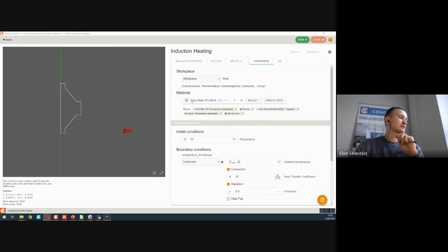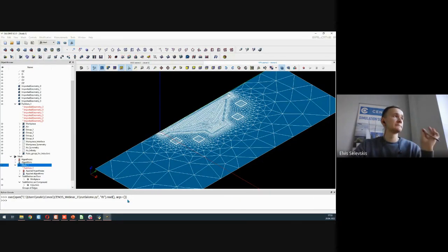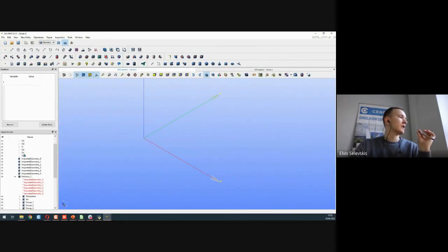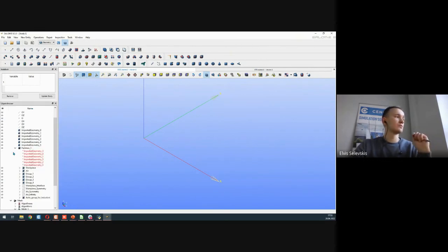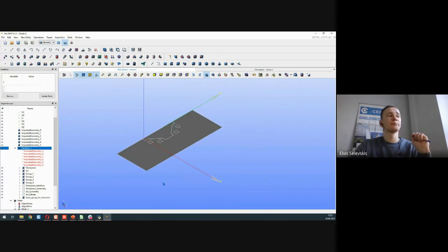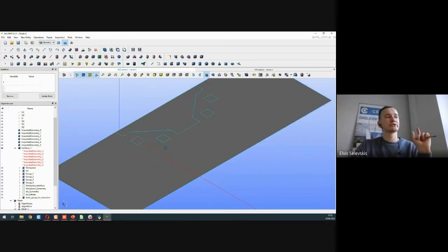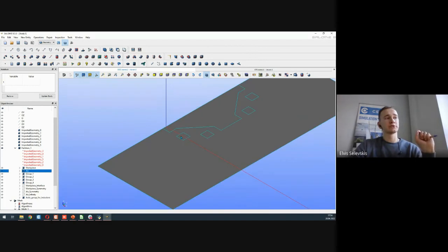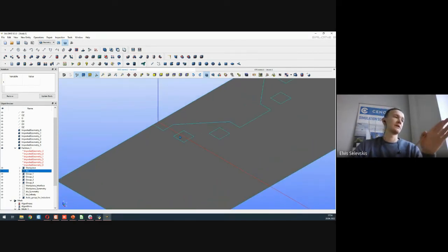The response there is that in Salome, in the case when the inductor would be hollow, if our inductor is hollow, all that we would have to do is add the hollow parts inside to the air domain. So the air would have not only the large block of air, but also the phases which are inside of the inductors.